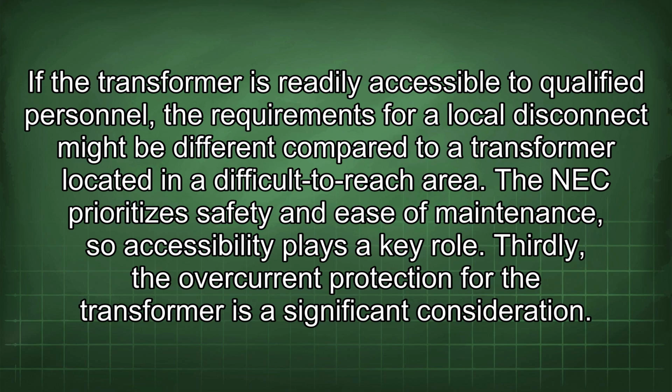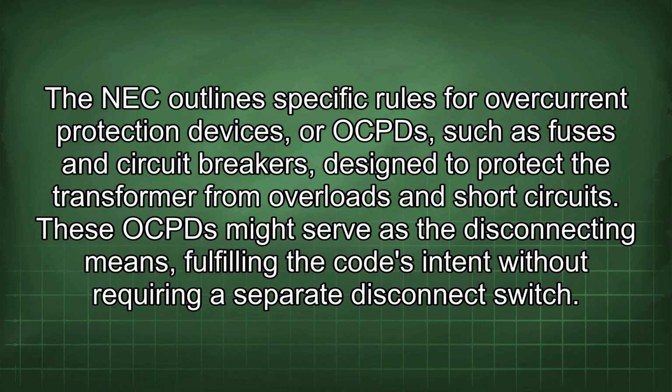Thirdly, the overcurrent protection for the transformer is a significant consideration. The NEC outlines specific rules for overcurrent protection devices, or OCPDs, such as fuses and circuit breakers, designed to protect the transformer from overloads and short circuits. These OCPDs might serve as the disconnecting means, fulfilling the code's intent without requiring a separate disconnect switch.